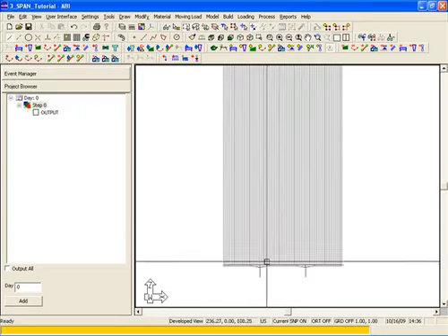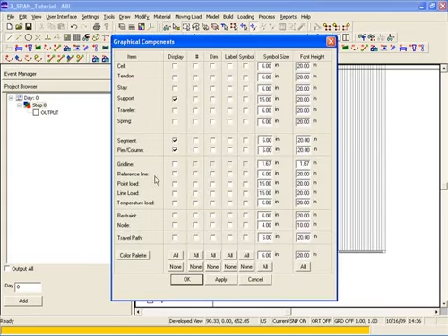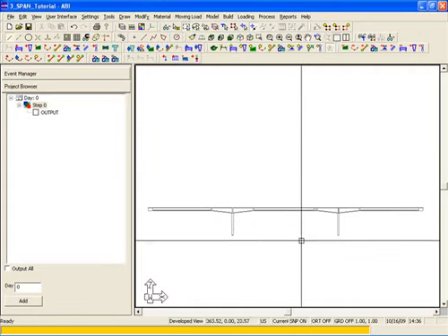To turn off the load in the view, we go back to Select Set View Items, and notice that line load is not selected, so we'll just say OK, and we'll go back to the default view prior to adding the line load.